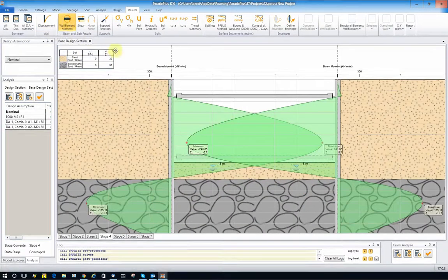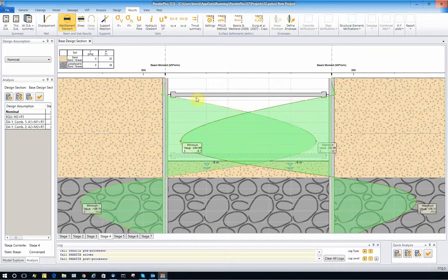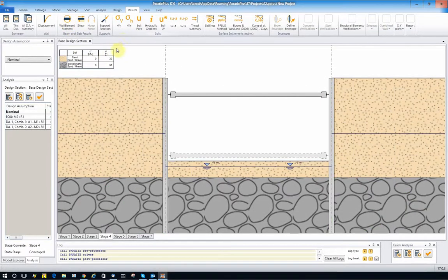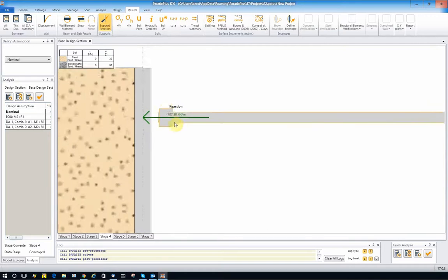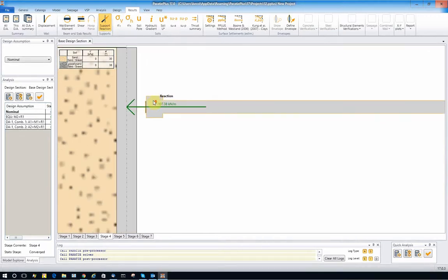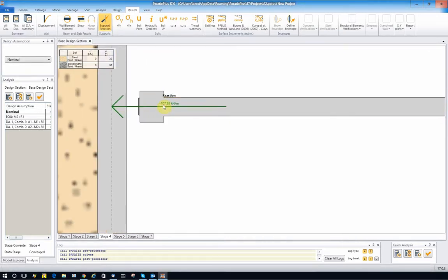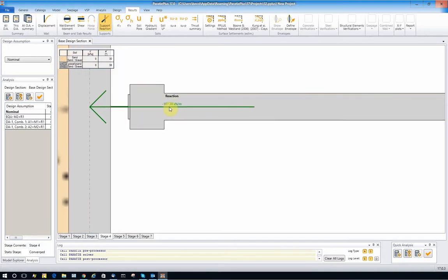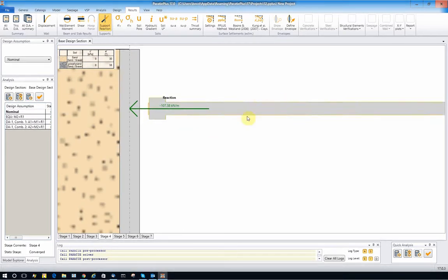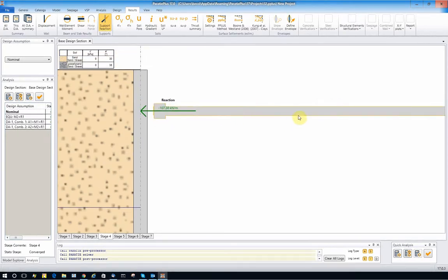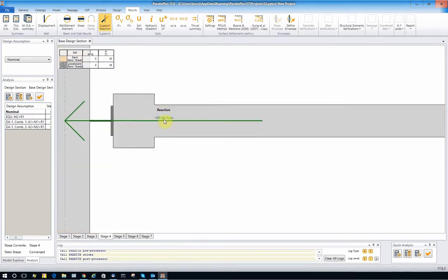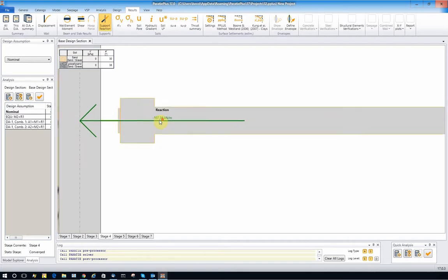Of course, there is also the bending moment distribution, and we can check also the axial forces. This is the result at this stage. It is negative, meaning compression, and we have around 100 kilonewtons per meter. If you remember that we considered one strut at 5 meters, it means that each actual strut may undergo around 500 kilonewtons of compression.